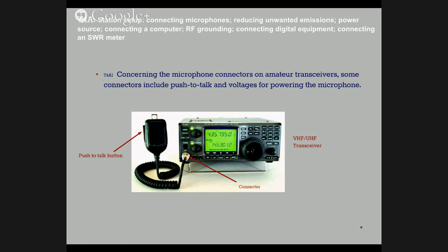And so a microphone from one radio, even though the connector might fit a radio from a different manufacturer, the pinouts might not be the same. And if you make the mistake of using a microphone with the wrong pinout, a lot of microphones are more than just microphones and a switch, but they might also have a voltage supply.